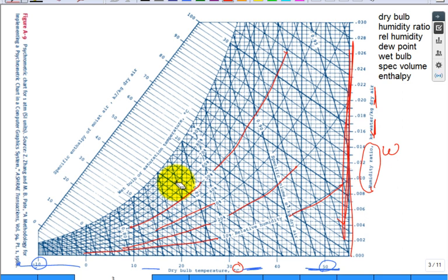If it starts pushing 60% humidity, people can feel it. If it starts pushing 40%, people can feel it. So 50% is the target. If you get 70 or 80%, there are going to be phone calls to every technician on campus: get over here and fix it. We are super uncomfortable. Or if it gets really dry. Okay, anyway, 50% relative humidity.